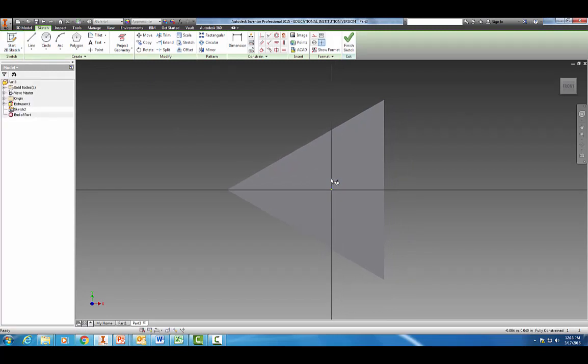We're going to make an ellipse on this, but first let's identify our axes. So we have 0.125. We're going to draw a line with a distance of 0.125. Hit escape.